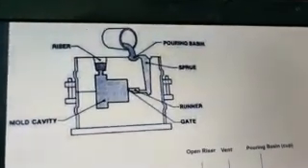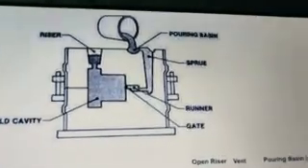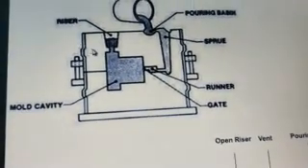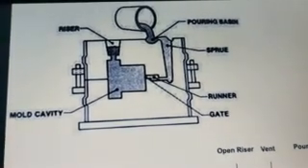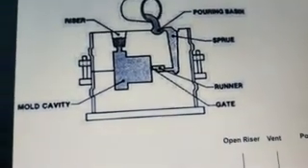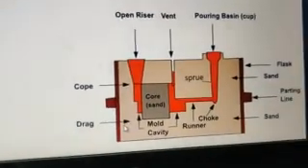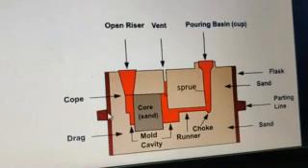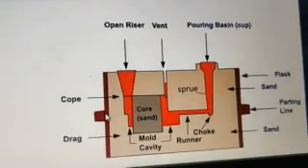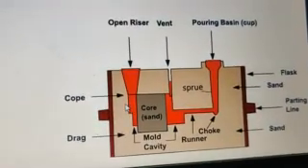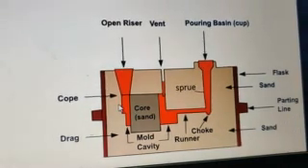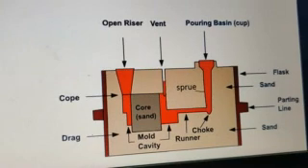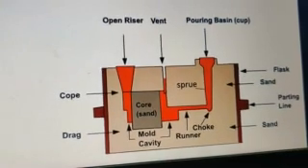And here you can see the arrangement of a sand casting molding flask, starting with the cope and the drag, the upper half called the cope and the bottom half called the drag. In cases where you have a product of larger dimension, we can have another one or two segments called the cheeks, the inner segments of your molding flask.